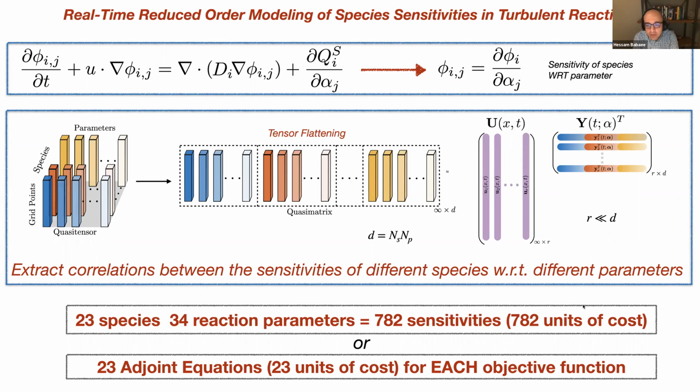If the problem is two-dimensional, even at low Reynolds number, I think I would still use adjoint because storage is not a big issue. But if the problem is three-dimensional with moderate Reynolds number, then adjoint could become problematic. You can compute the gradient of your objective function with respect to the shape perturbation using this approach. The Y coefficient would have the shape parameter, and U would show you the sensitivity, so you can easily compute the gradient using U and Y because you have the full dimensional sensitivity.